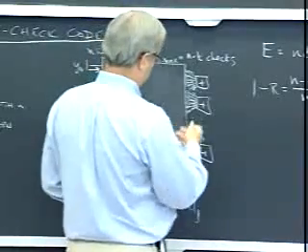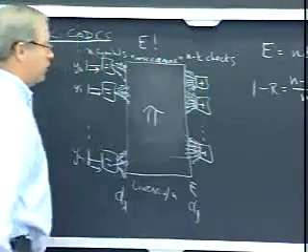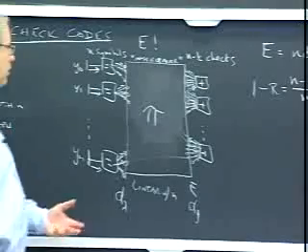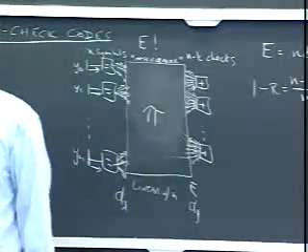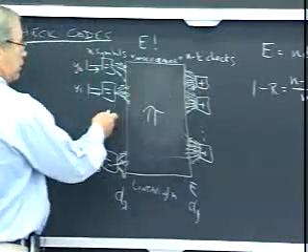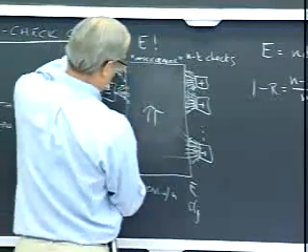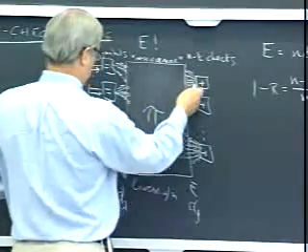We get a bunch of weights for 0 and a bunch of weights for 1. We add them all up, and that gives us a recomputed likelihood, a message consisting of probability of 0 given what we've seen so far, and probability of 1 given what we've seen so far, that now goes out. Hopefully that's got some improved information in it now, coming from all different parts of the graph, extrinsic.